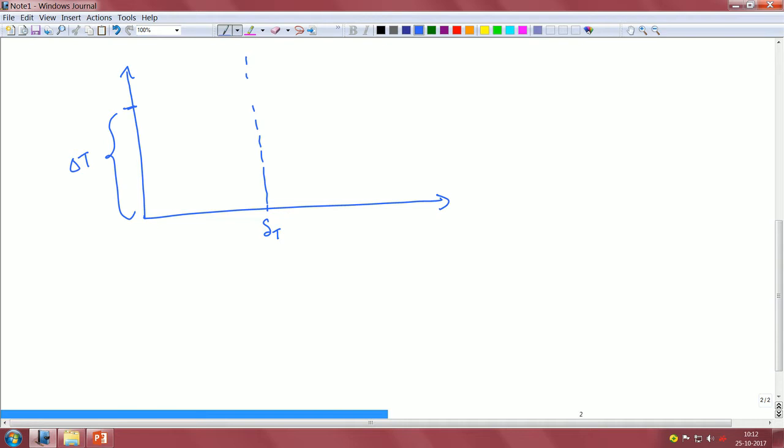Okay. So, in this particular zone, for Prandtl number much greater than 1, if you look at this particular situation, within this delta T, from here to here, what you are going to get is that the temperature starts at the maximum at the wall, and slowly goes down to something like 0 here. It's more asymptotic. Okay.